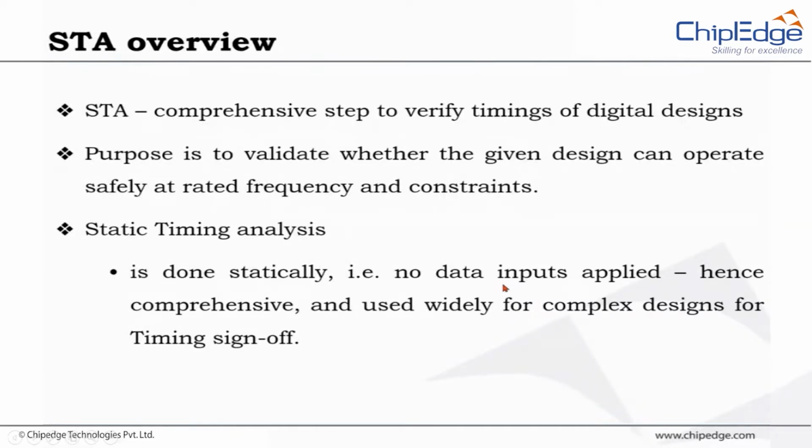For that, you need to have vectors generally, right? But static timing analysis is smart to actually create these transitions inherently in the tool. And you're not providing any kind of a vector from outside. All you're trying to say is, this is my timing requirement, go and analyze. So it statically passes all that.